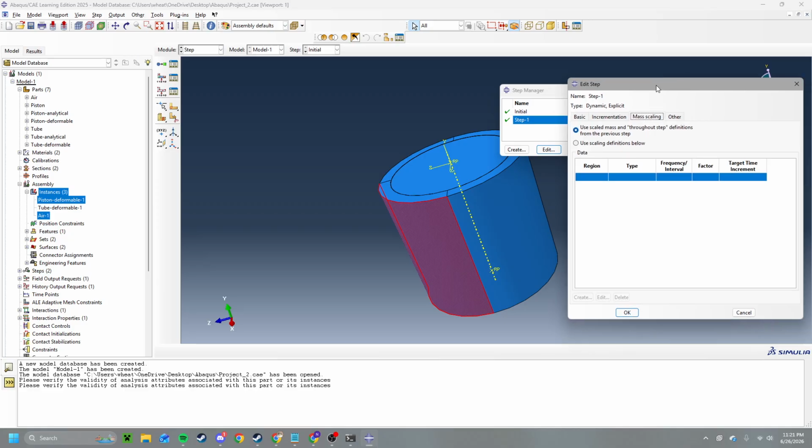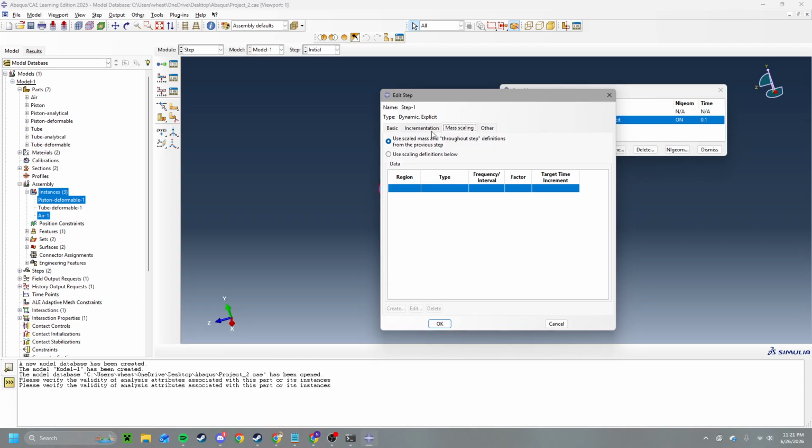An important thing is Eulerian components, you can't really use mass scaling, because the way that they work, they use the mass fractions. So if you use mass scaling, it makes it way too stiff slash rigid, which kind of makes it not as useful.